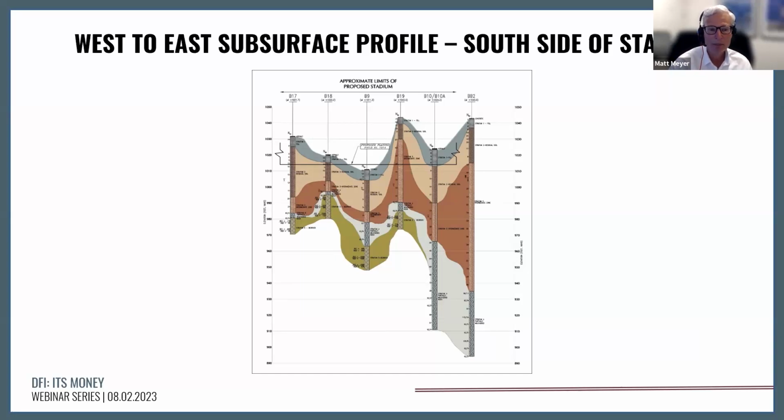So starting from top to bottom, the gray depicted layer you see there, the first stratum, that is an uncontrolled urban fill layer. The tan depicted stratum, that is the residual soils or the residuum. The maroon depicted layer is what we're going to term the intermediate zone soils or the saprolitic soils. They're higher in SPT N value than the residuum.